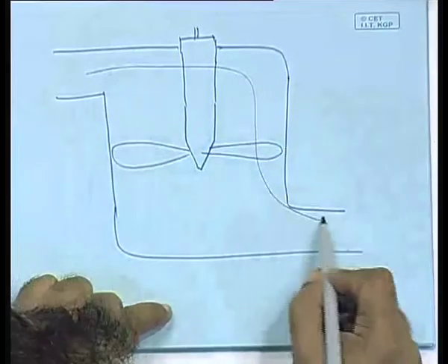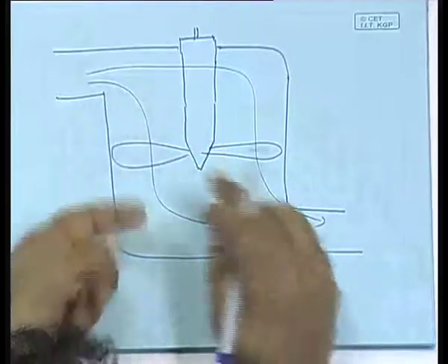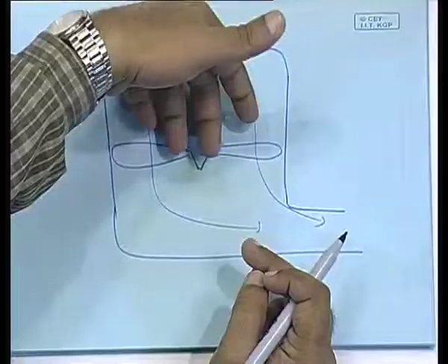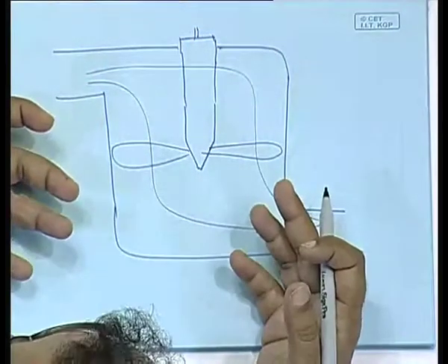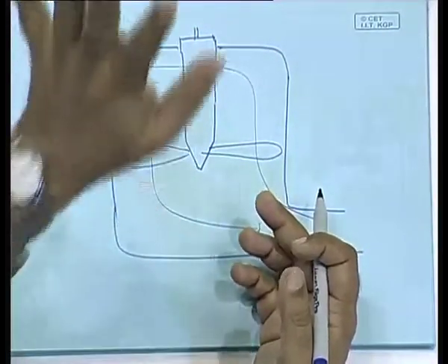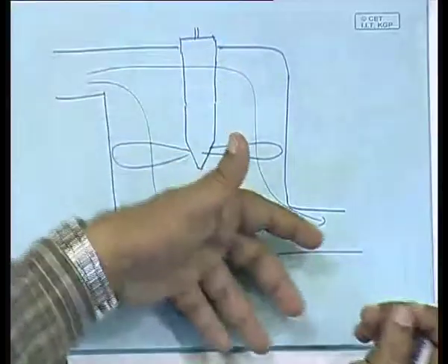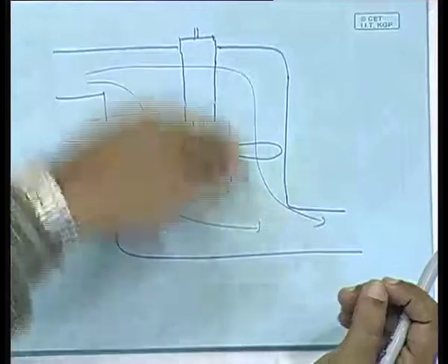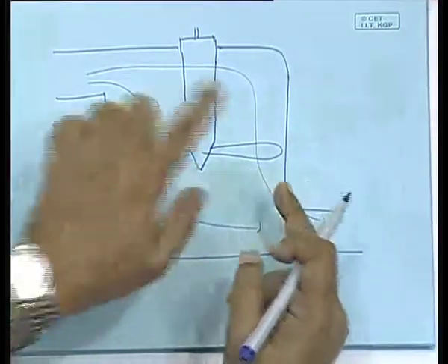It is like a fan. So, as the water comes and flows, the fan rotates, and therefore you can see that the fan is always in touch with the water, and you are not using the kinetic energy of water really. You are only using the pressure of the water, flow of the water to make the turbine rotate.